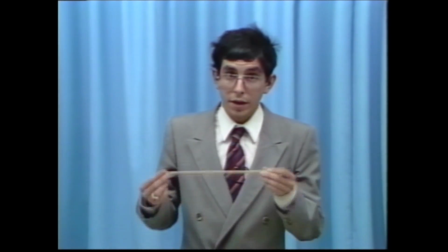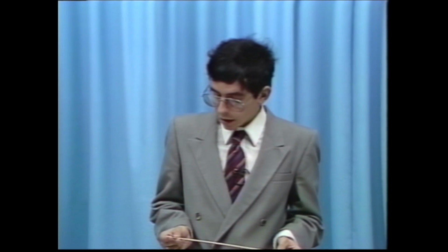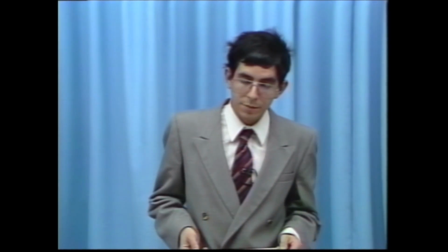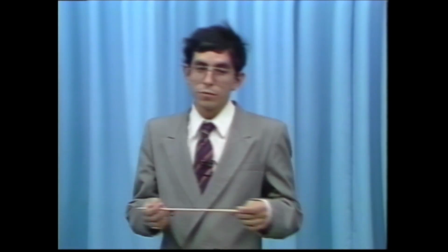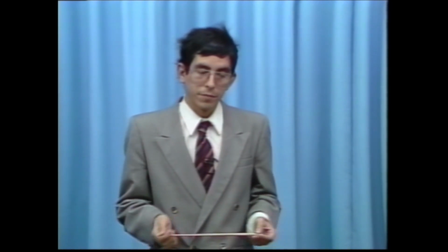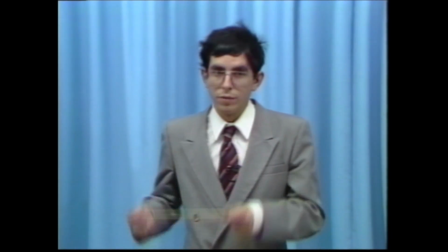Okay, well actually, let me give you a more generic answer, and that is that in the realm of hybrid engine concepts, there are really a nearly infinite number of schemes by which you can incorporate ramjet operation and compressor turbine operation. Several schemes that you're alluding to try to match a ramjet with rocket performance. So for instance, you might consider a ramjet which at some point in its flight can transition to pure rocket power.